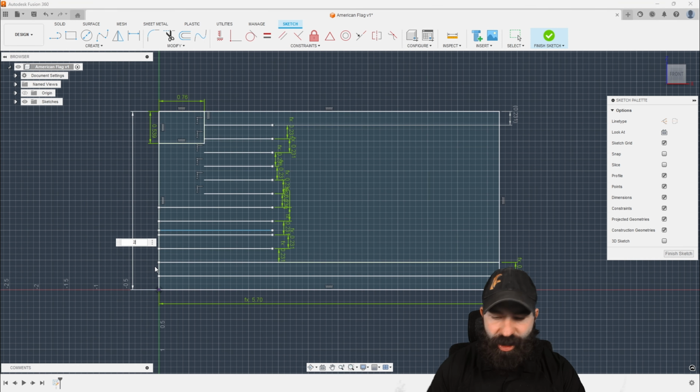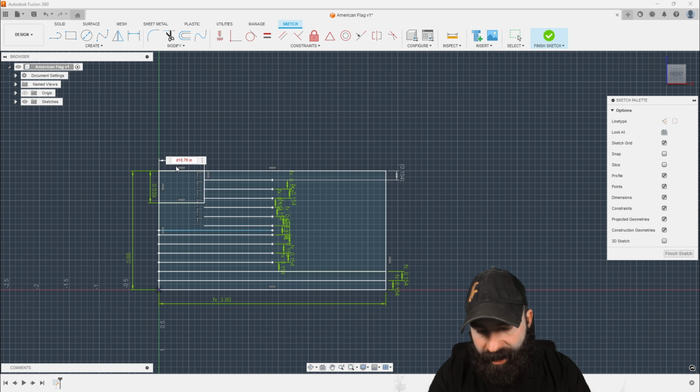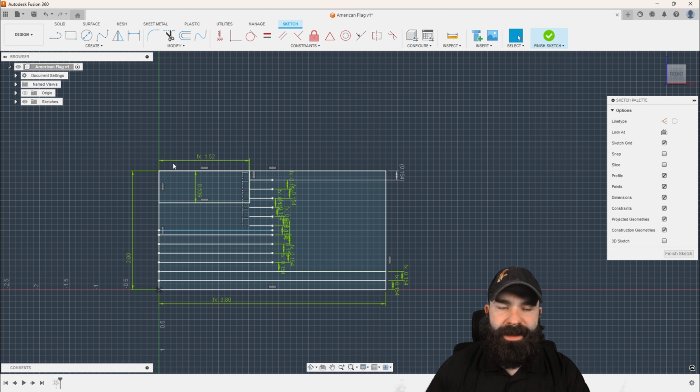So if we went back to a 2 here and I hit enter, my lines are now shrinking and growing based on that dimensional callout. Again, if I take D1 and times that by 0.76, we have that ability to control anything and everything. So actually, I'm going to go 0.76, and we're going to delete the inch here real quick, times D1. And we do need to put inch in here in some way, shape, or form, or else it's going to come out in millimeters.